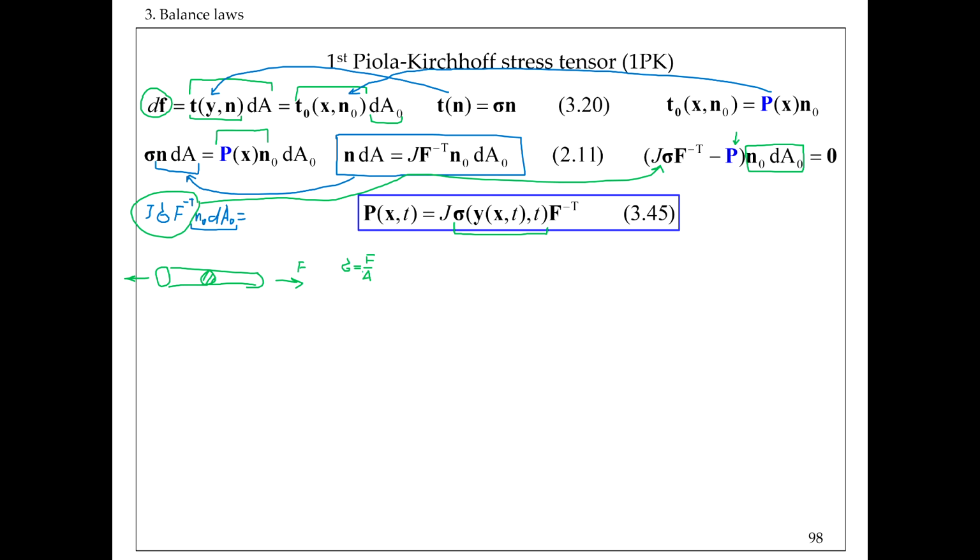But if you divide by the area in the initial configuration, before it starts to change, because you didn't want to measure the change in the area, or it was not possible, then you are in fact measuring the same force divided by the referential area, and that would be a measure of a component of P. It's very simplified, with A0 being the initial area, and so there will be a difference in the factor of the area as you transform it.